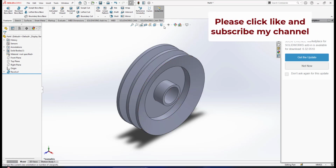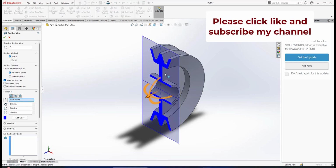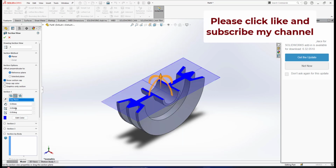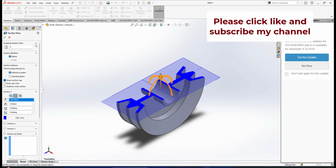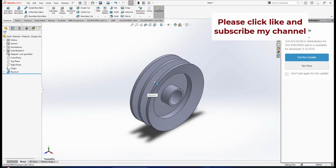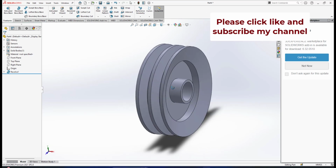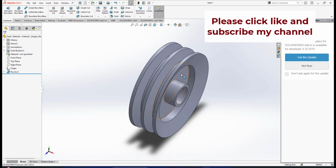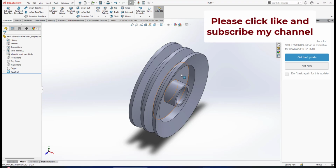At the top of your screen here, number 4 is the section view. You can go for the front cutting plane, or the top cutting plane, and also you can set any parameters here to do further cutting planes of the section. But this section view is just meant to aid our view to see the inside of our component. So I think that's all for your pulley. So we have the pulley, and that's how you do this base profile modeling approach. For our base profile model, we are using revolve, we are not using extrude.